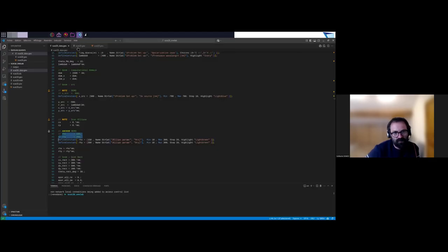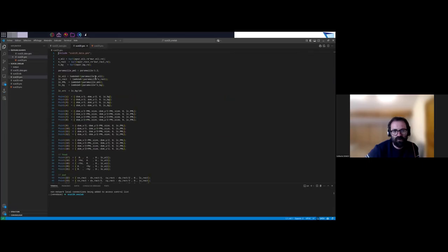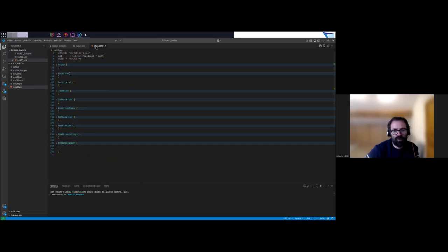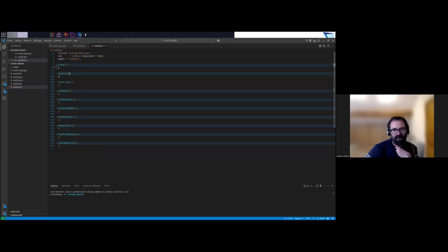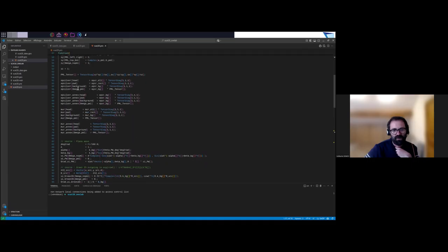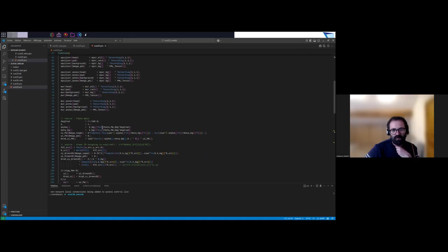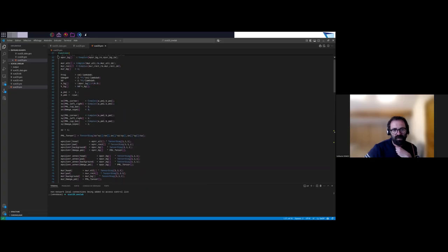Because as you can see, the model itself consists of a .geo file, where I'm not going to comment, it's just a geometry definition, and of the .pro file, which can be quite big, because we define all these GetDP things, which I'm not going to go through, to bind all my domains to the Gmsh mesh. So it's just the definition of the domains. Then you can define many functions for the permittivity, the incident source field, etc. So it can get quite big.